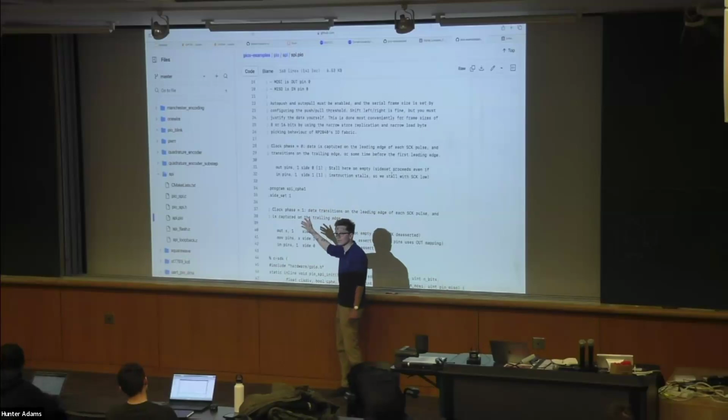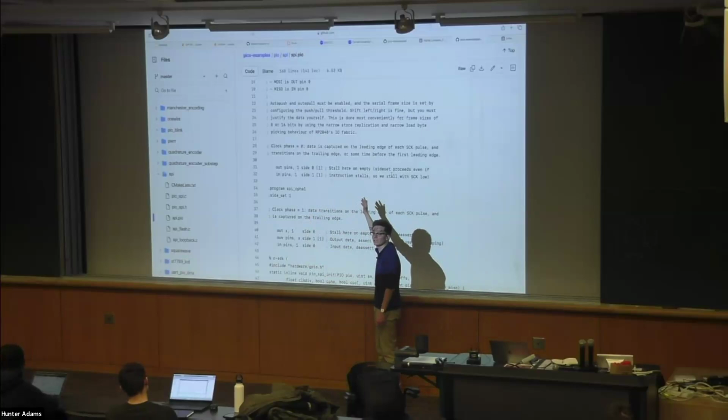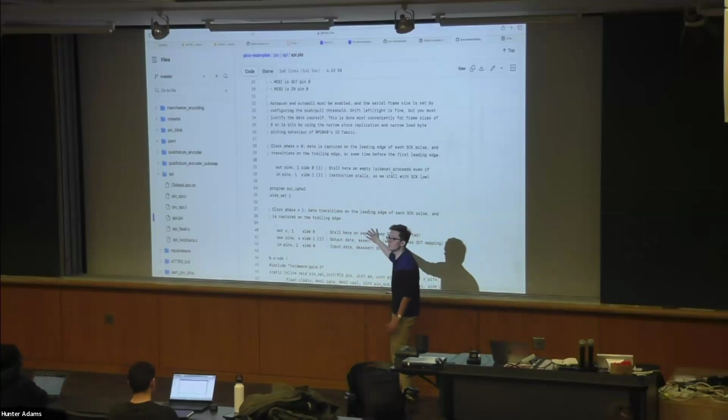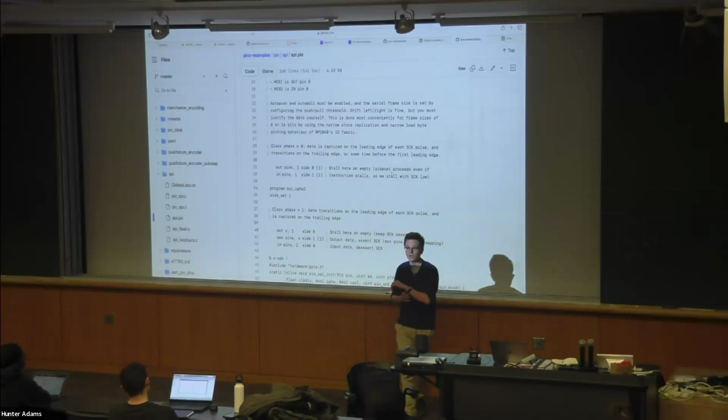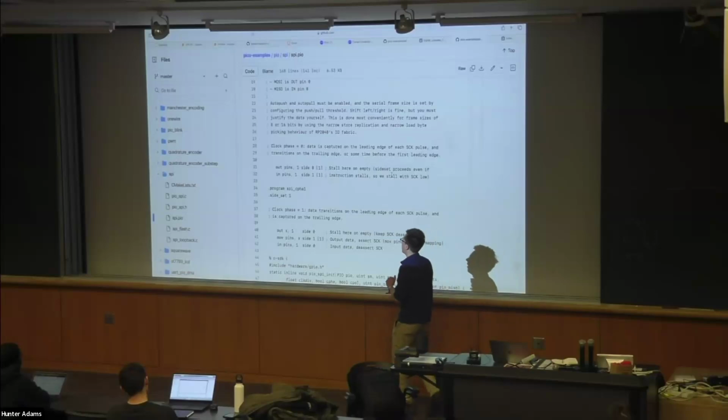So what this means is you've got 2 SPI peripherals on the RP2040. If you need a third, build a third. If you need a fourth, build another one and another one and another one, right? You could build a whole bunch of SPI channels, a whole bunch of UART channels. We could look at I2C implementations here, and build a whole bunch of new I2C channels. Or, as we'll discuss, if you're trying to communicate with something strange and non-standard, you could build yourself a non-standard interface. VGA is going to be one of these non-standard interfaces.